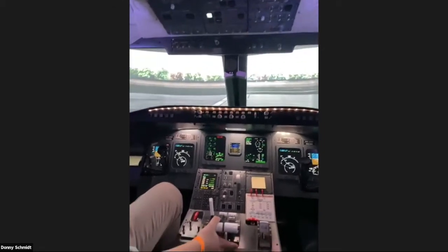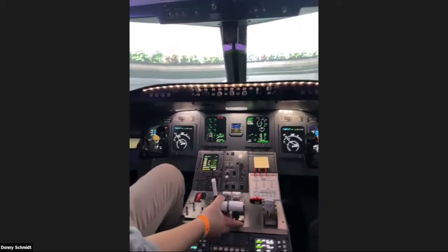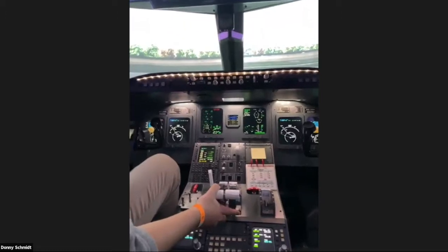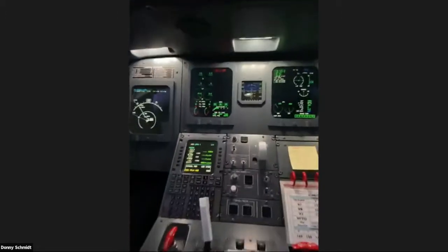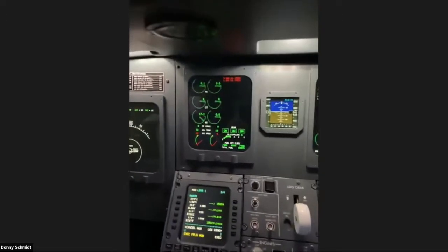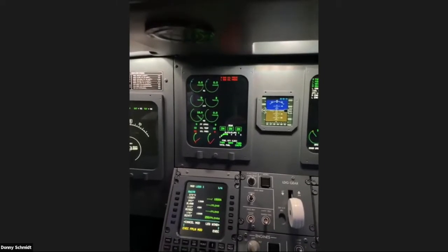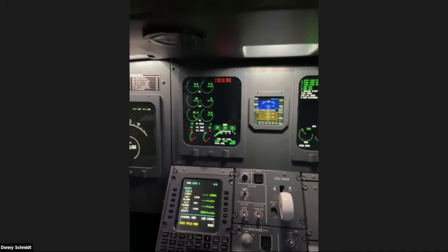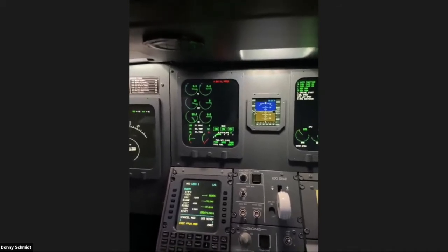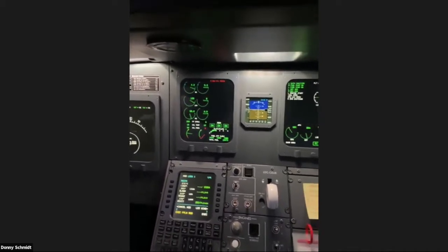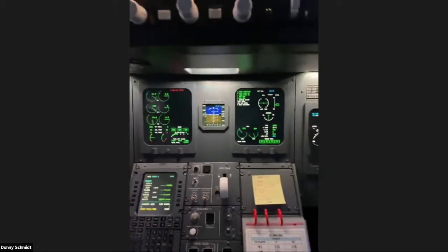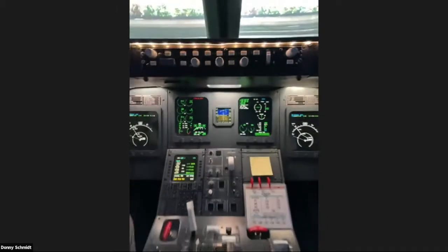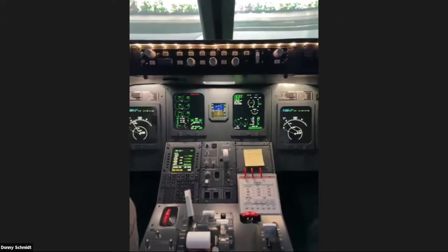So currently the APU, or auxiliary power unit, is running, and that's where we're going to get the bleed air that's required to get the engine started. We can see gauges here in the center are what are spooling up as those engines get going. I introduce fuel to it right now. And now you see the first turbine fan stage. Cool. Starter still engaged up top. And once it stabilizes around 40% power, it'll be